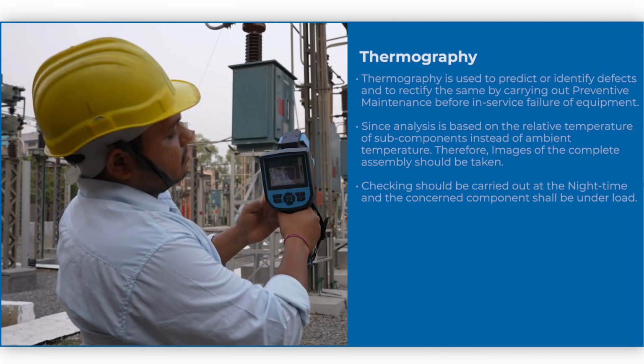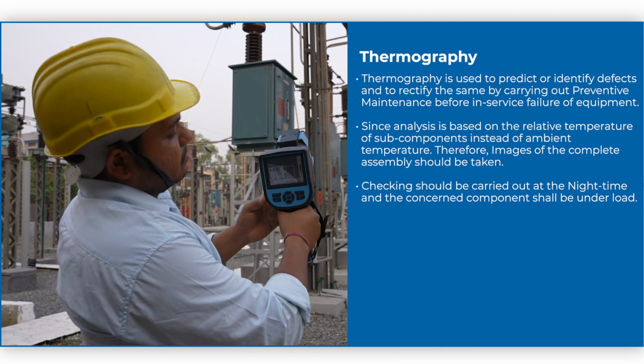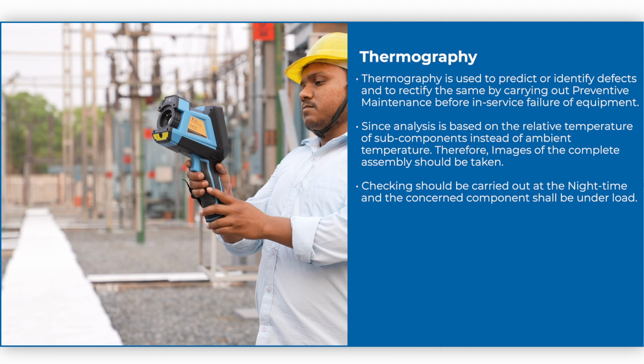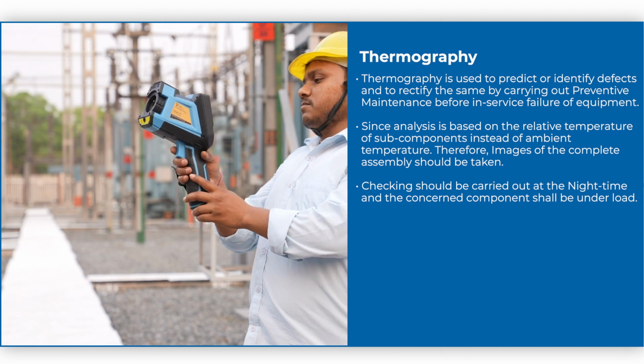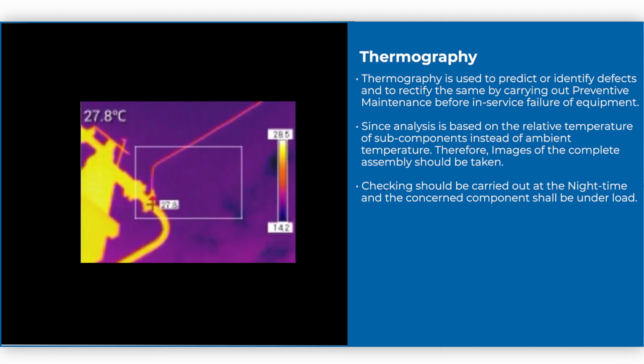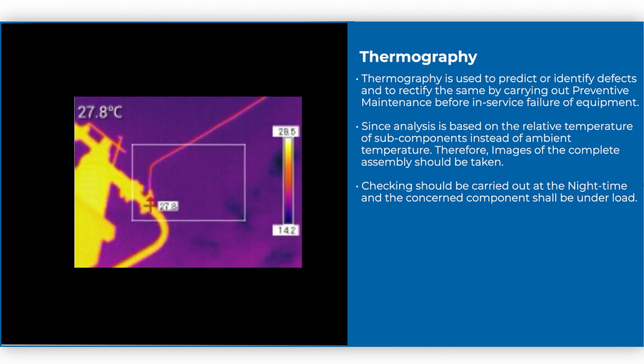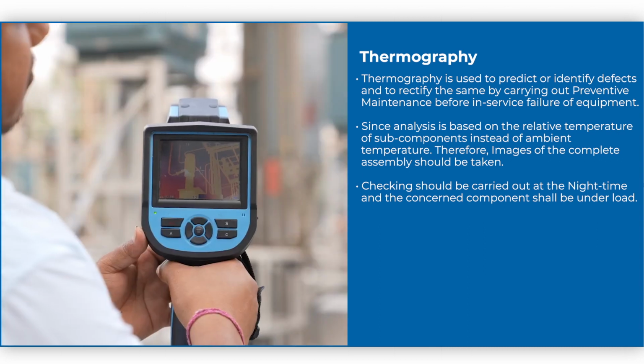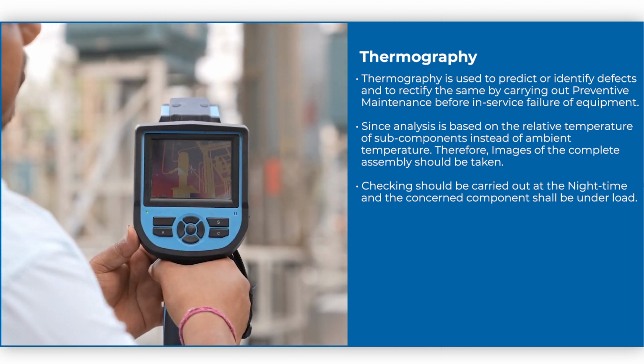Thermography. Thermography is used to predict or identify defects and to rectify the same by carrying out preventive maintenance before in-service failure of equipment. Since analysis is based on the relative temperature of subcomponents instead of ambient temperature, images of the complete assembly should be taken.